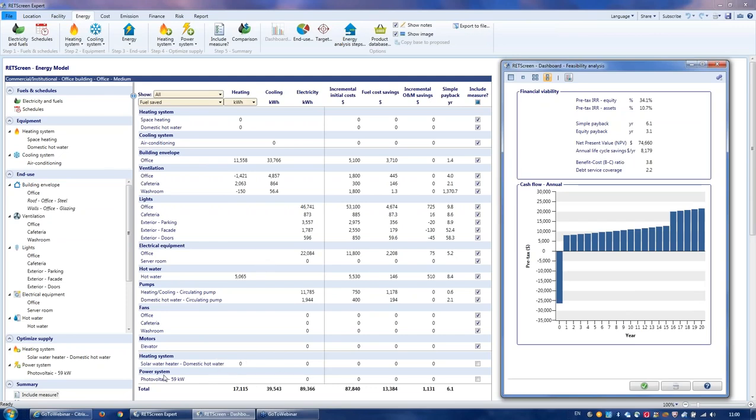Now, the virtual energy analyzer will automatically go in and also size a solar water heating system and a photovoltaic system. It's usually unticked, meaning it's designed, etc., and the user can decide to add these. Typically, they tend to be more costly than traditional energy efficiency measures, but they also help you reach green building standards, reducing greenhouse gas emissions, and particularly for net zero energy buildings.